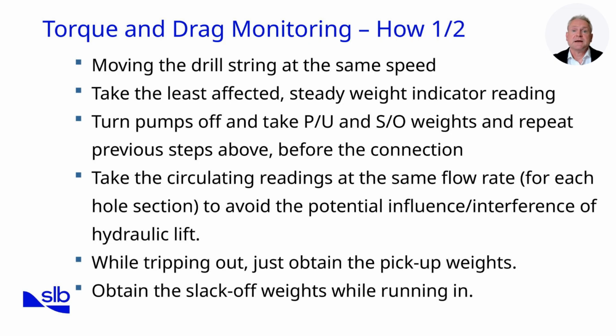Third, before making a connection, the pump should be turned off. Take pick-up and slack-off weights in non-circulating conditions, then repeat with circulation if required. This allows us to distinguish between hydraulic lift effects and true drag. Additionally, circulating readings should always be taken at the same flow rate within a hole section. This prevents variations in hydraulic lift from being misinterpreted as drag changes.